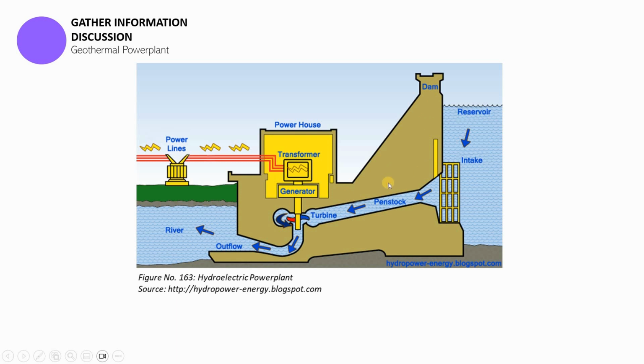Okay, and then it actually connects to a lower area here, which is the continuation of the river. So this dam, what's behind the dam is a water reservoir, and yung opening sa may bandang baba is called the intake. And then this area right here between the intake and the turbine itself is the penstock. So yung pressure dyan is quite high. Gravity kasi is allowing this flow through the penstock.